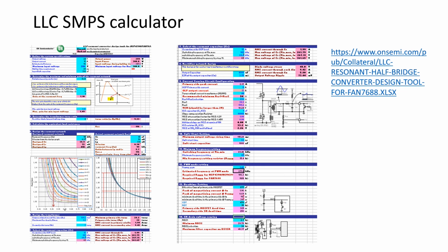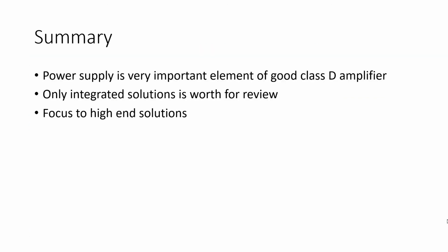Typically, gapped ferrite cores are necessary to get the right values. And you should do the process from scratch each time the output voltage and power specifications change. That means for each modification of the output power and voltage you need to do a new resonant tank design. But it is an amazingly good power supply for audio amplifiers.